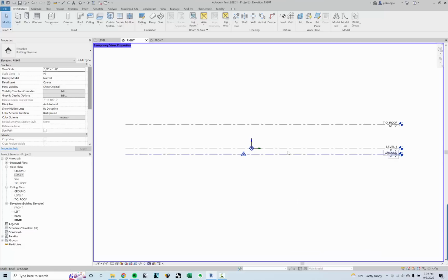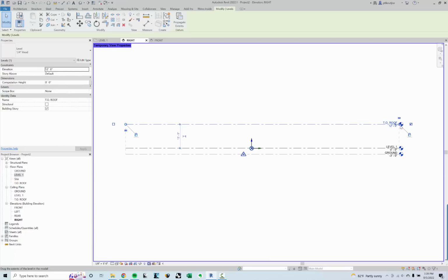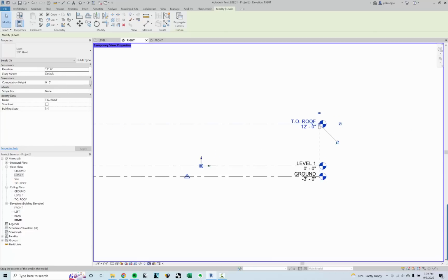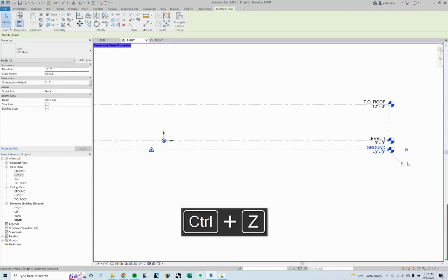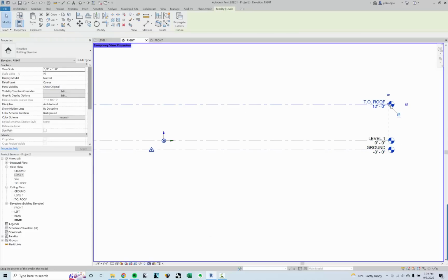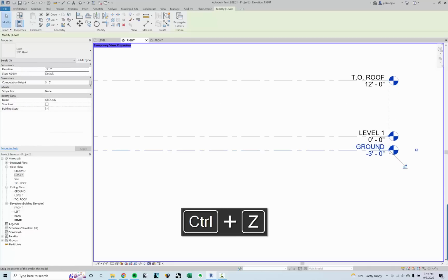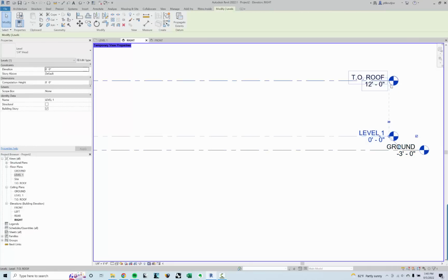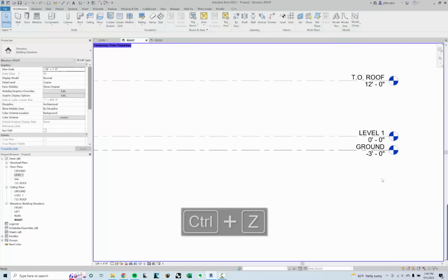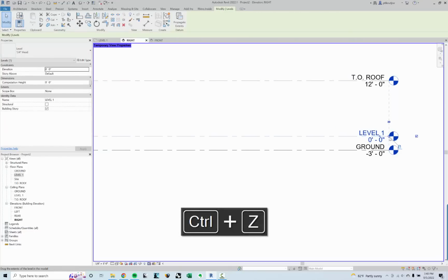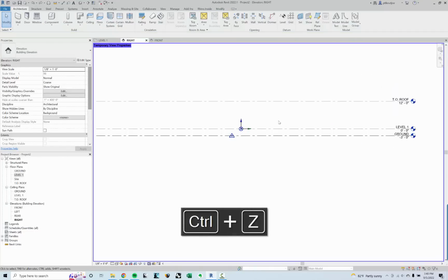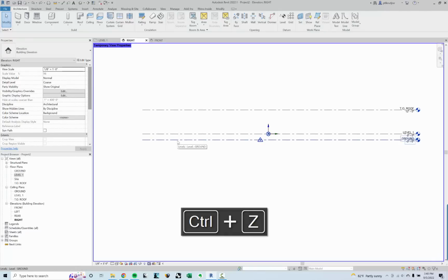Now, the one thing you might notice is that the origin point is kind of in the middle here. It's because I shifted the whole entire building and these are in a weird spot now relative to it. I can click and drag this little dot, which will move them all relative to each other. They just have to be constrained, right? If I unlock that, I can move this. Oops, that's not actually it. I'll unlock that, and then I can drag this one independent, and then it won't be constrained to there anymore. But I actually want to try to keep that relationship, so it helps me keep the levels nice and clean. Same thing on that side. Again, it's something we'll clean up as we go.